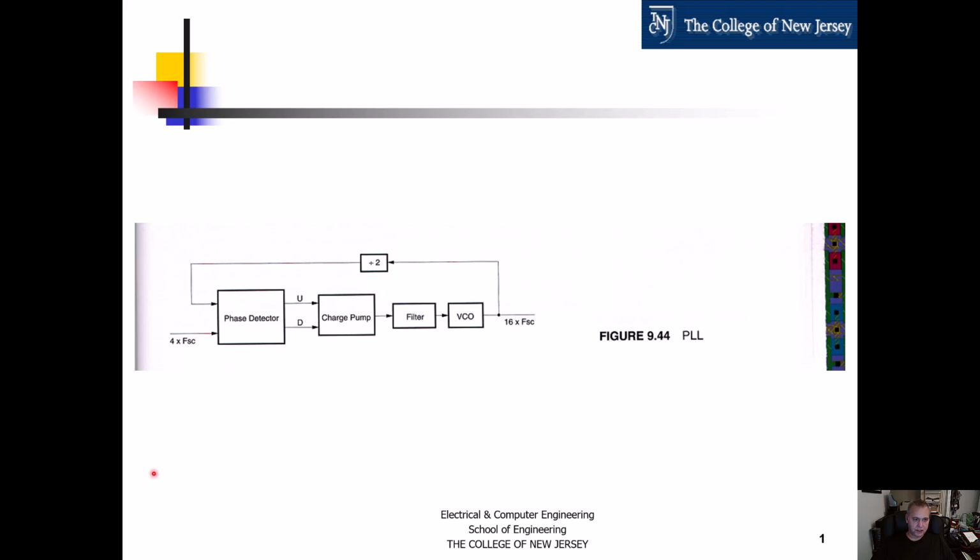This is a presentation on a couple of mixed signal VLSI systems. One is going to be a phase lock loop and the other one is going to be an analog to digital converter. So first, the phase lock loop, this is the block diagram of the system. It is what is called a charge pump and current starved inverter voltage controlled oscillator based phase lock loop.